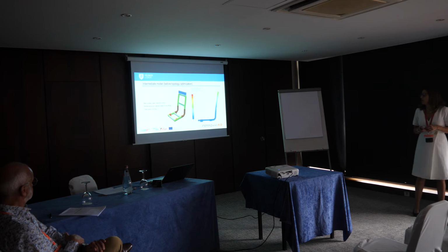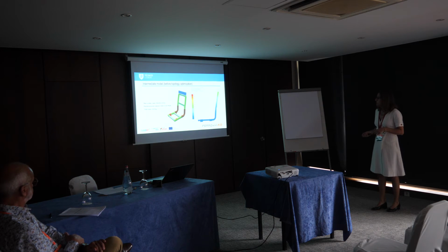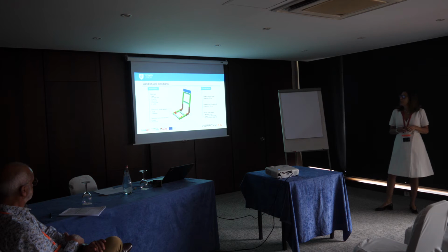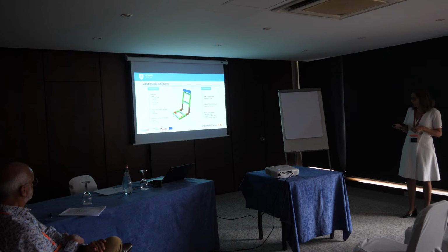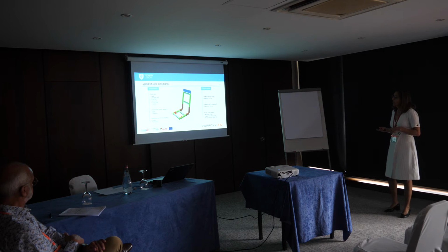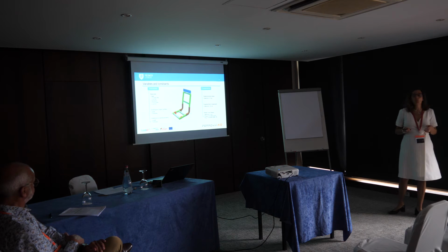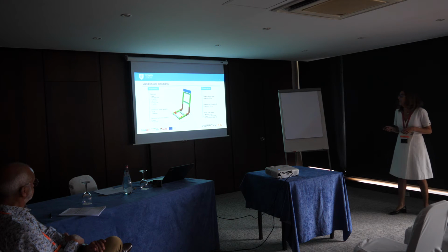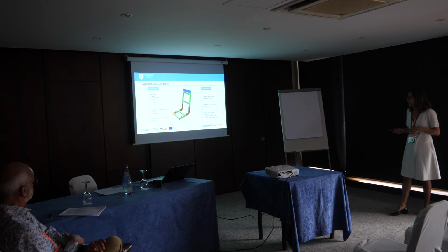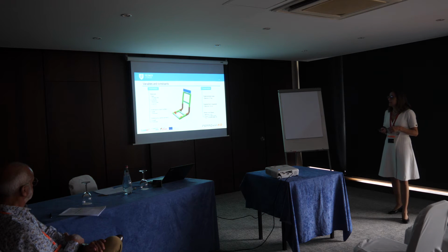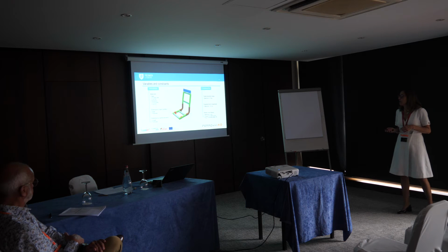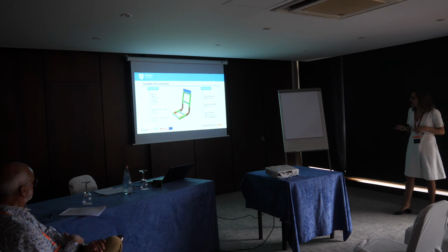And at this moment we decided to optimize the model. To optimize the model, we define these variables and these constraints. In terms of variables, we define the Young's modulus and the Poisson coefficients for the two materials, steel and aluminum alloy, the dimension of the main profile, okay, this one in green, the width and the thickness, and the dimension of the reinforcements, namely the length and the thickness.